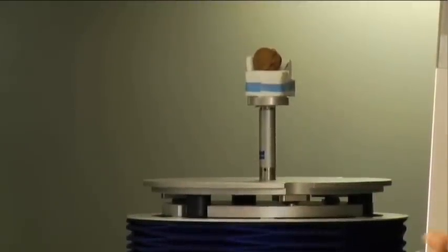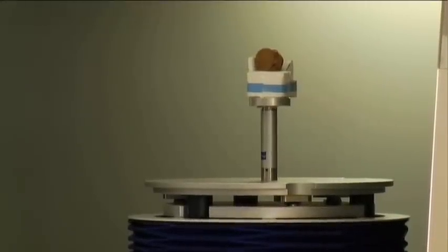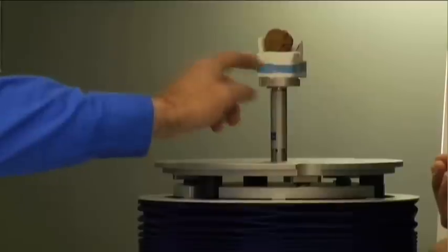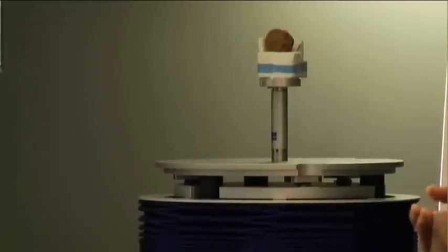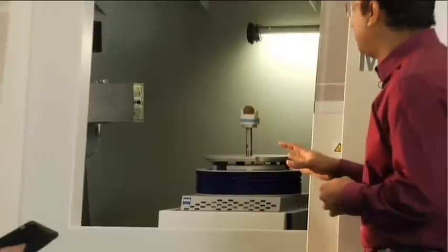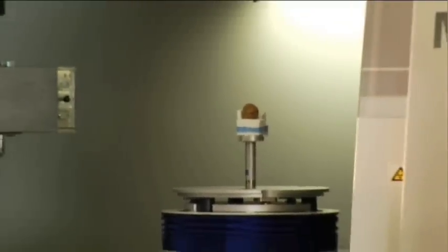We use expanded polystyrene or styrofoam. Basically, it is so low density. You're saying the styrofoam here is the fixture. Yes. All right. The styrofoam is our fixture. So X-rays go through the styrofoam, and you don't see it. So the fact that the styrofoam is actually sticking up in front of the walnut isn't really going to affect it at all. It basically doesn't affect the scan at all. Please close the door here. All right.